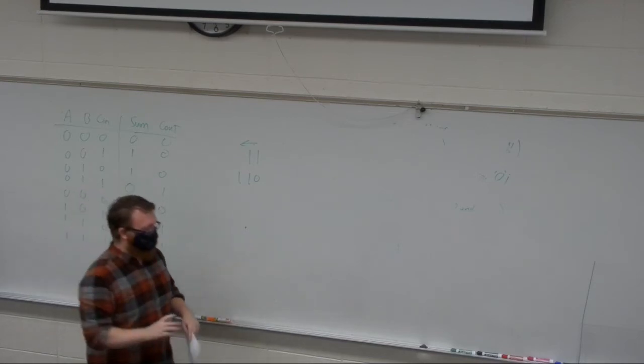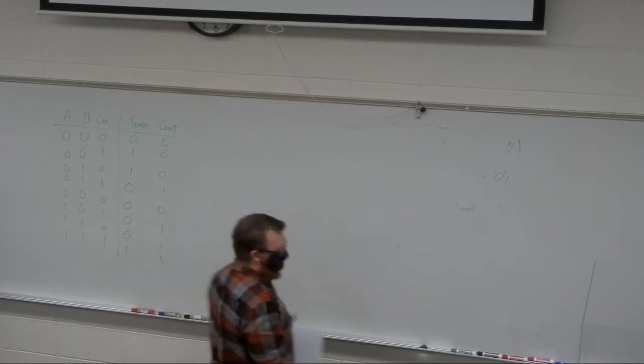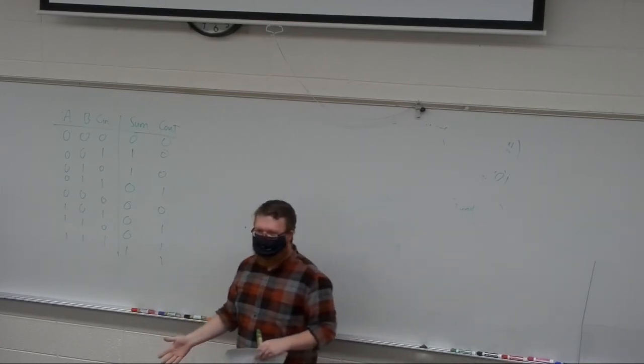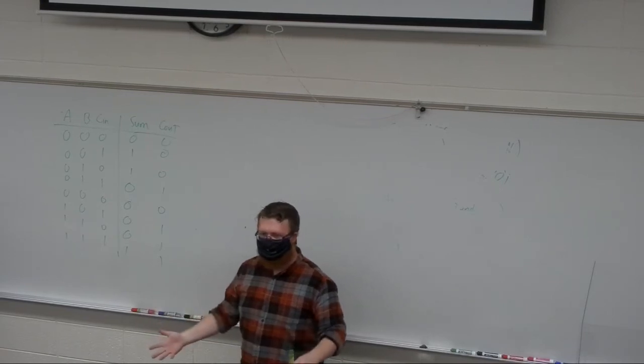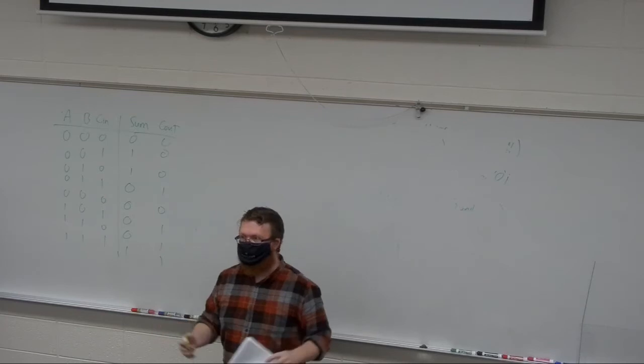So let's make a shifter in VHDL. So this is just me throwing what we would call combinational logic at you, and then showing you how to make this in VHDL. So you see lots of VHDL examples of what we would call simple devices.